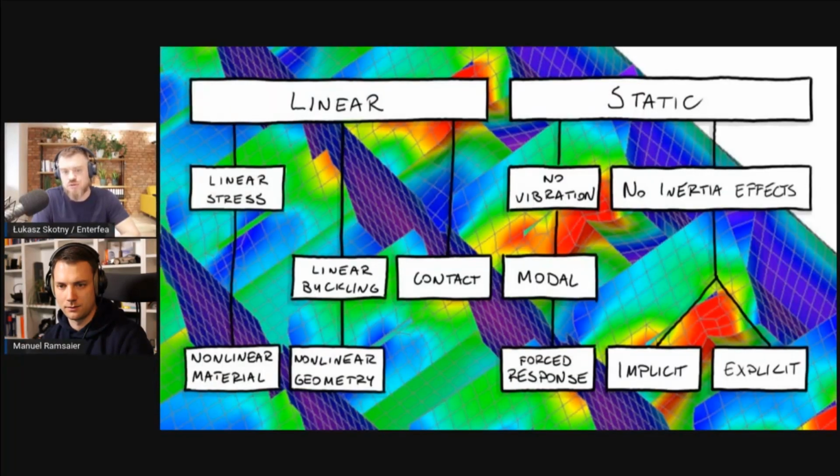Yeah. The problems start to come when people do plate structures. Shells and stuff. Yeah. Welded from plates, like big filters and, God forbid, shell structures. And then suddenly you are trying to approach a much more complicated phenomenon using the same simplified tools. There are no friendly equations for plate and shell structures that you could use. So for beams, it was: take your critical load, critical force, critical moment, put it into an equation, compute 2 numbers. You can do a very simple Excel sheet that does it. And ta-da, you have the capacity. There are no equations for shell and plate structures.